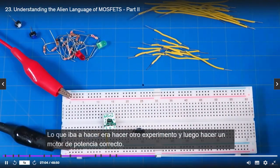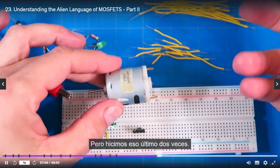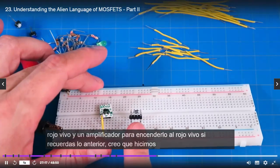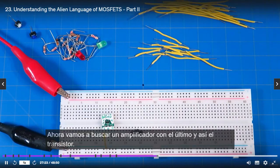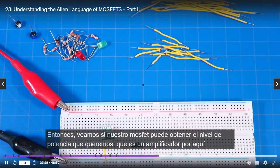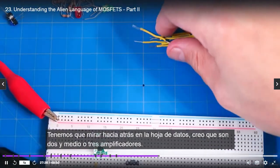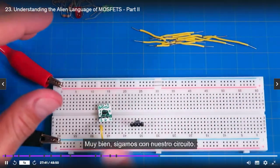Now, what I was going to do was just do another experiment and then power a motor, right? But we kind of did that in the last one twice, so I thought let's do something that requires even more current. This is going to take at least an amp to turn this red hot. If you remember the previous thing, I think we did 200 milliamps, 300 milliamps. Now we're going to go for an amp with the MOSFET instead of the transistor. So let's see if our MOSFET can get us this power level that we want, which is an amp through here. Now, this particular one I think will flow a couple amps. We'd have to look back at the data sheet. I think it's 2.5 or 3 amps, and then the other P channel can do I think 5 or 6 amps. All right, so let's keep doing our circuit.